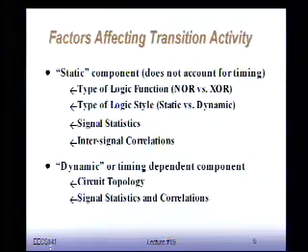And this transition activity is really a function of, I can manipulate this in many different ways. The type of logic function, for instance, as I'll show you in a minute, different logic functions will establish different transition behavior. The logic style, remember static versus dynamic, I already discussed. Dynamic switches more often than static because I always pre-charge it, and every time it's a 0, I basically discharge it. So dynamic logic typically has higher power than static.